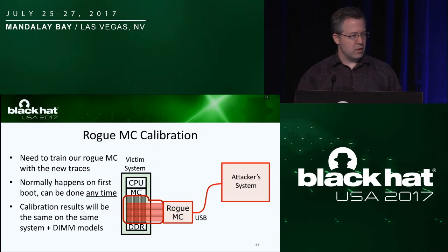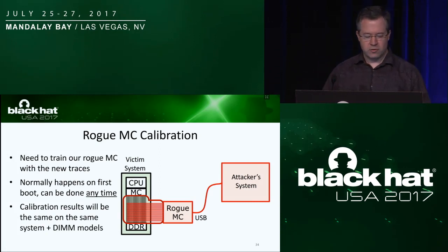So the other thing that was mentioned was calibration. This is a requirement for any memory controller attaching to a DIMM. It's not so much of a handshake per se, but they do send some bits back and forth to measure round trip times and essentially calibrate that the data and the clock are aligned for successful reads and writes. They try to form an eye where your data is aligned right in the middle of your clock window. So that's part of the purpose of the calibration.